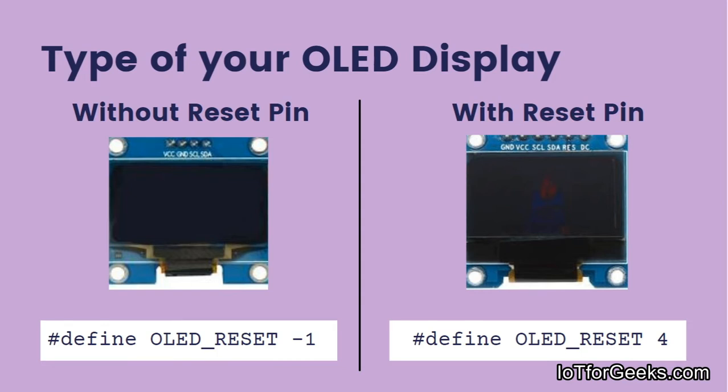It indicates your OLED display has no reset pin. And if your OLED display has a reset pin, then connect that reset pin to a digital pin and declare it with that digital pin as shown on the screen, like #define OLED_RESET 4, because the reset pin is connected to pin number 4.